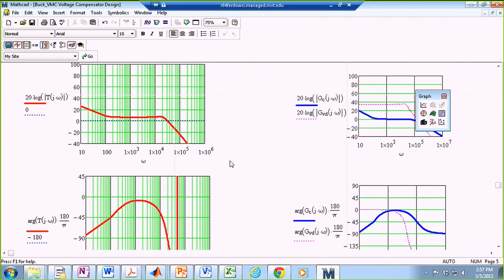You can identify there is a 0 over here because my Bode plot basically breaks. Instead of continuing to go down with a slope of 40 dBs per decade, all of a sudden it comes back up and gets flat. Then the rest of the poles in the system kick in over here. The reason that you add a 0 over here is to add extra phase margin, because zeros give you positive phase angles. So your phase margin increases.